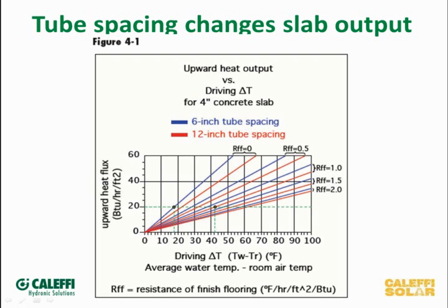Now, one thing that you want to look at, this was a great little graph that John put together, I should say. And what it does is it shows you the different outputs with different things that you can play around with when you start looking at doing a radiant slab, whether it's a new home or you're going to do a retrofit or a remodel project and you're thinking about doing a radiant slab. What we did here is we took a typical concrete 4-inch slab, and we wanted to show you how the heat output changes and how it varies based on the supply temperature here across the bottom, as well as the